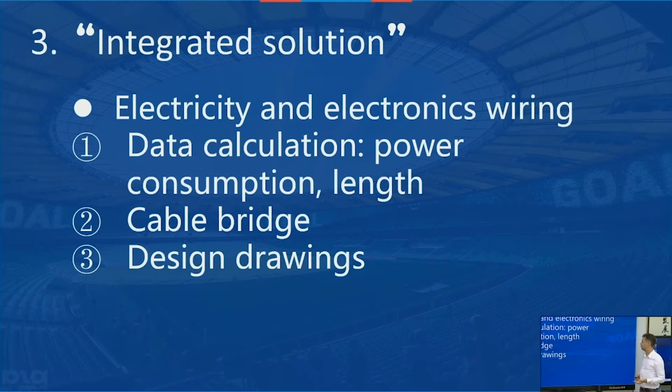Electrical drawings, so all the wirings, power cabling, signal cabling, all is done here. So we decide how much power we'll take, from which sources, how to bring the cables, where exactly these cables will be, what kind of cables we will use, cable types, and so on, and number. And of course, signal cables layout, like what kind of cable we will use, mostly fiber, where exactly we'll put that, what kind of cable trace we'll use, and so on and so forth.